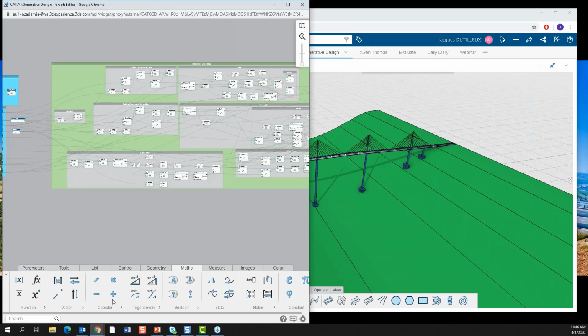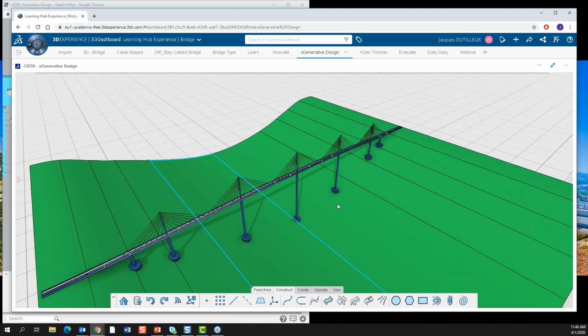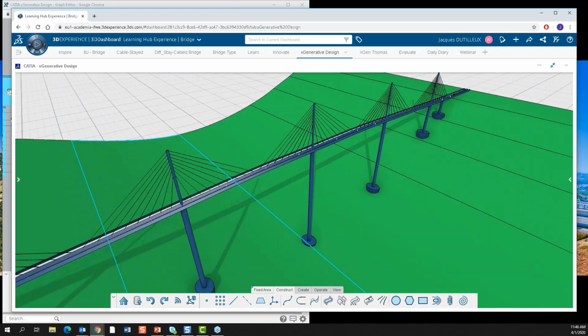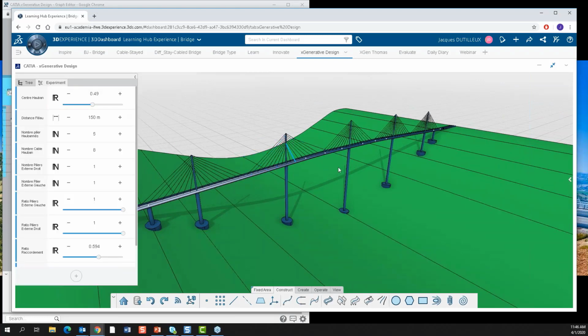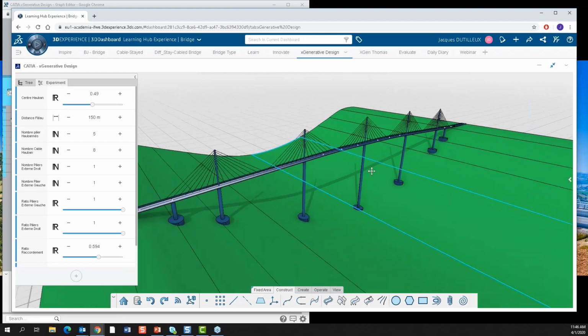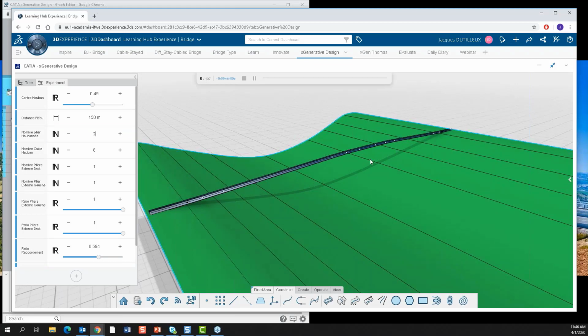Okay, I got another question, to show us more about your project. Okay, so this is my current project, as you can see. It's the stackable bridge that I got today, but it's not finished. It's only the second draft improved with the body on the skeleton. So you can see that I put some geometry over the skeleton, and the main aspect that I was talking to you about is the capacity to change some parameters. So for example, if I want to change the number of stackable pillars, I just have to click on this and the geometry will directly change.